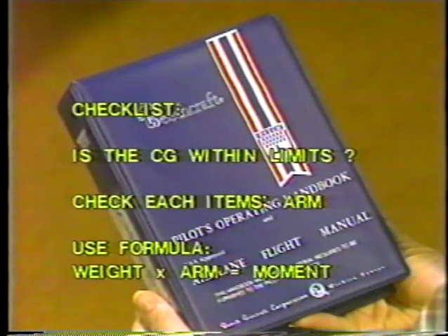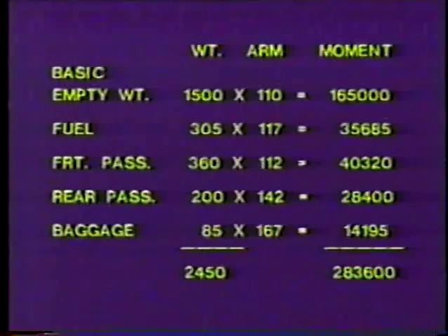Also, loaded under these conditions, is the center of gravity within limits? Begin by consulting the pilot's operating handbook for this particular airplane to find each particular item's arm, and then use the formula weight times arm equals moment. Your worksheet should now look like this.